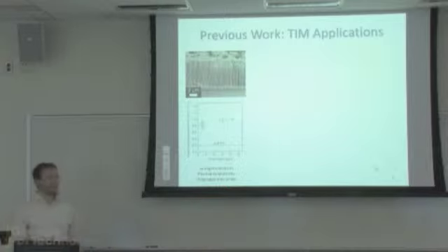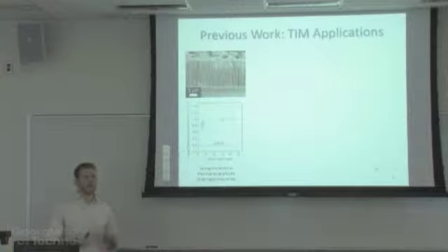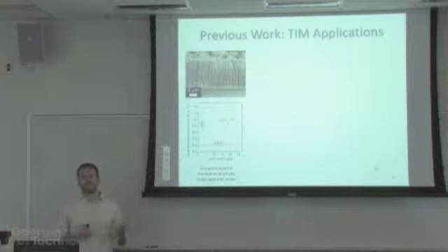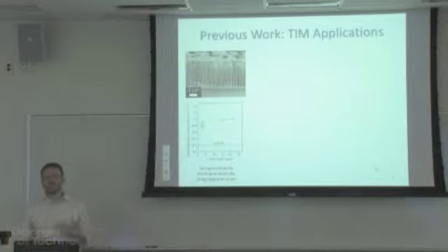So we created wide area arrays of polythiophene nanofibers. We electrodeposit these in a template, and we can use these as heat transfer materials. We've shown that over a wide array of heights, we can actually increase the thermal conductivity compared to bulk polythiophene by about a factor of 5. If you include the void space in the array, it's actually a factor of 10 increase compared to the bulk